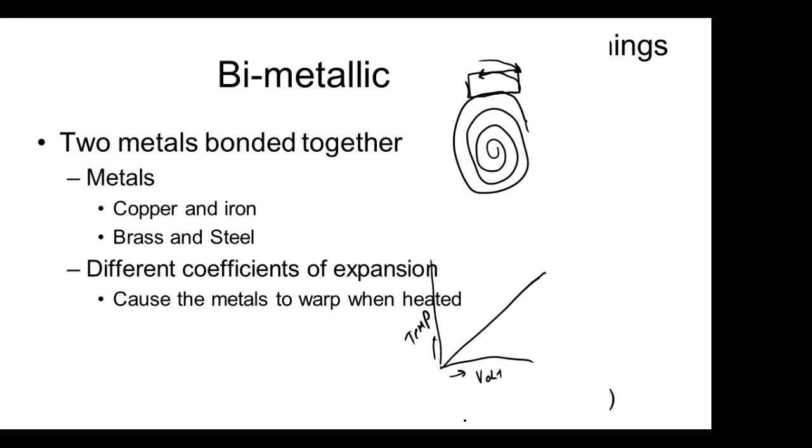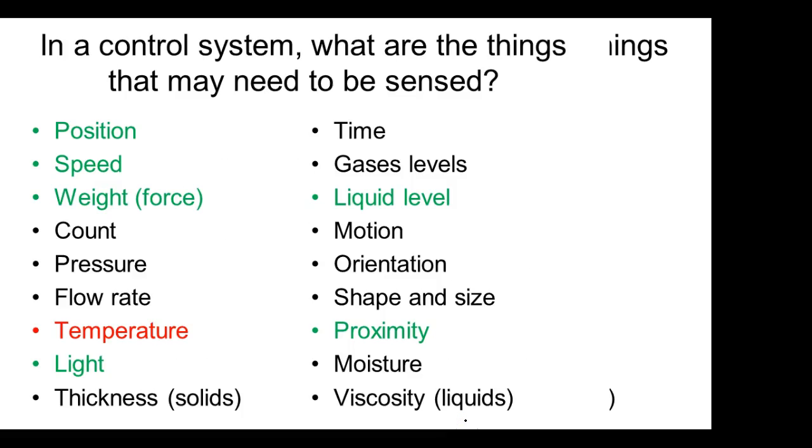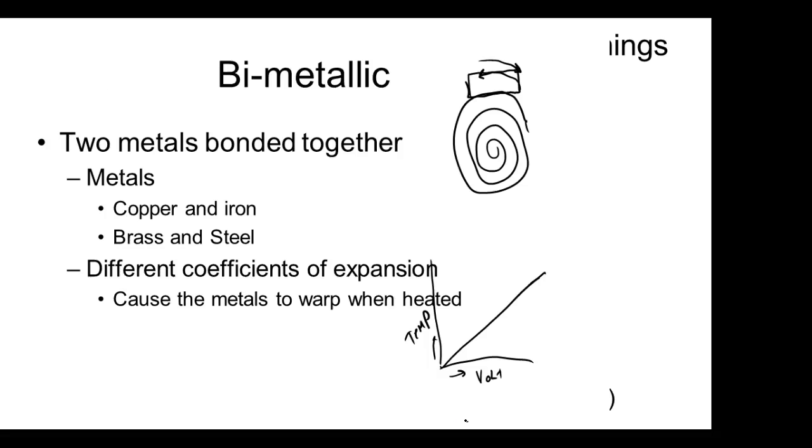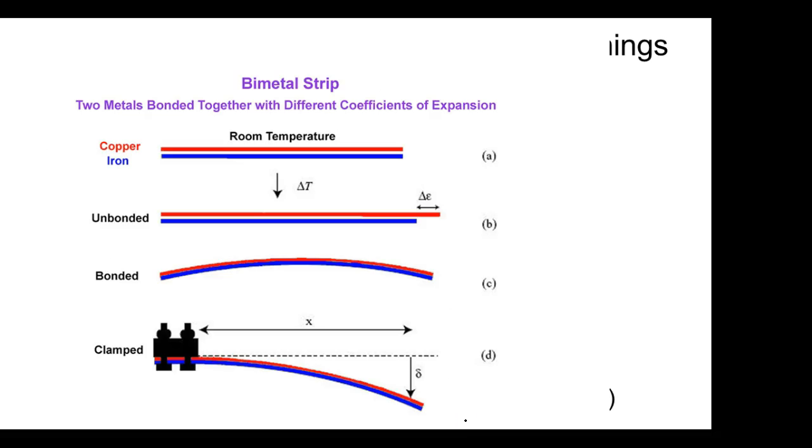So if it's got a positive temperature coefficient, that usually means its opposition would go up when the temperature goes up. If it's positive, its opposition would go up as the temperature goes up. If it's negative, it would do what? It would go down. Most of your thermistors are negative. So y'all can look at this. Like I said, this is an open thermostat.